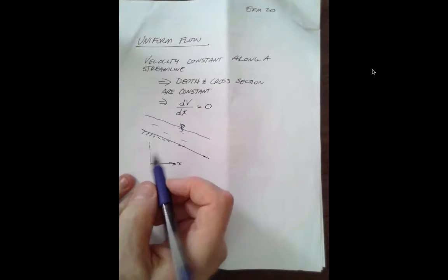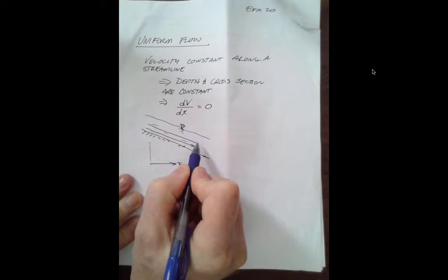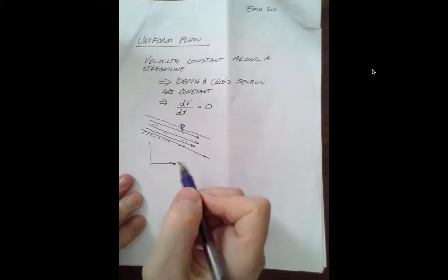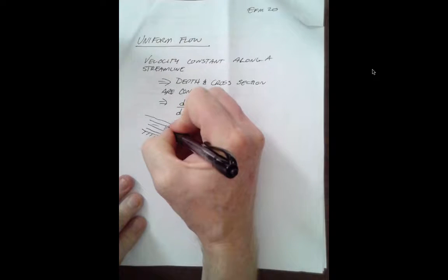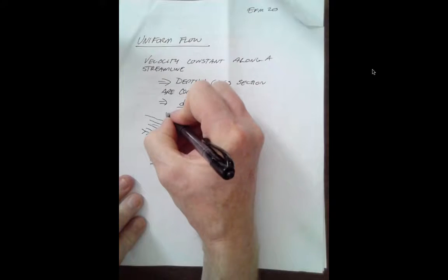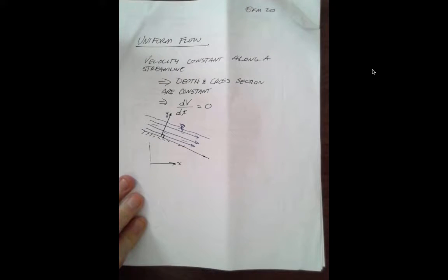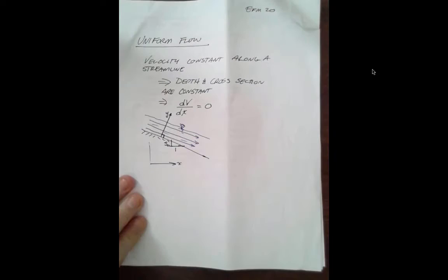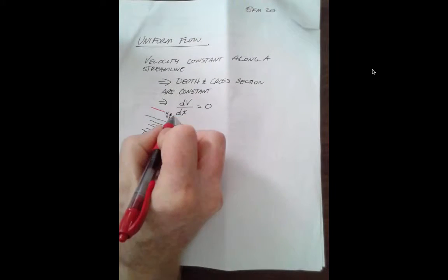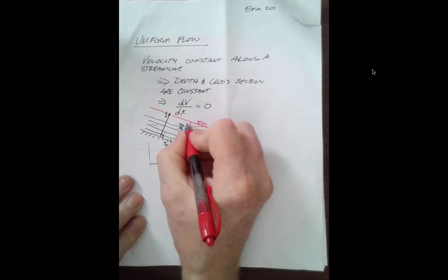In uniform flow, we would have the property that the streamlines are parallel to one another. We generally measure flow depth in this direction. The usual symbol is y. The bottom slope, exaggerated in this drawing, is S0. The energy grade line, which lies above the hydraulic grade line, so there's our EGL. Its slope, the usual symbol is S sub F.